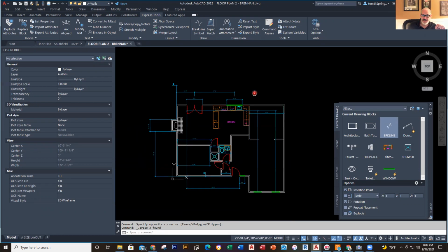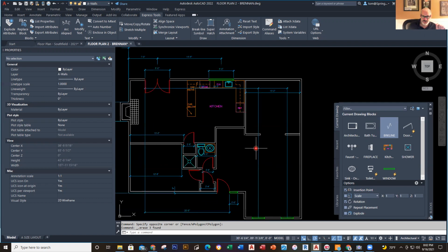So you guys are doing good, and you're asking good questions. In any situation, I think I've dimensioned the stairs, but you might have to think that through a little bit. The stairs should work out pretty well. There are 14 risers at 9 inches. You're going to get it pretty close. If I don't have a dimension for every little thing, just fit it according to the drawing. Just do what makes sense. There might be one or two dimensions that I don't have on there because it was getting so cluttered, so I stopped putting dimensions in. But I gave you pretty much everything you're going to need.